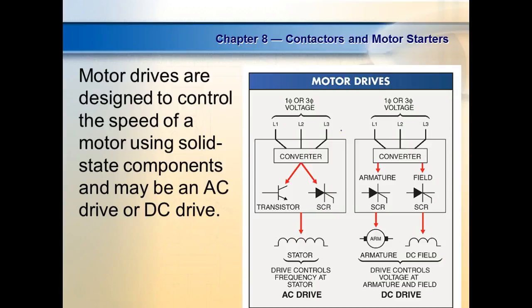And if you've ever seen the spacing between the rotor and the stator coils, they're just right there together. I mean, you can hardly put a cord in there. You get a little bit of rust on there, then your rotor would rust to the stator or those poles, and now you've got a problem. So what they did at U.S. Steel, if they were going to be down for a while, they left power on all those DC motors. They left power on the field.